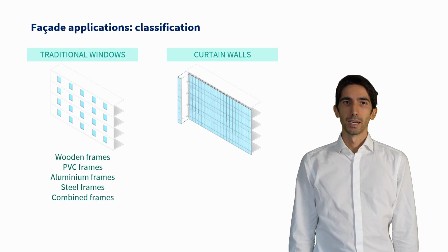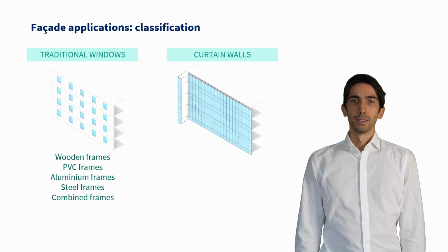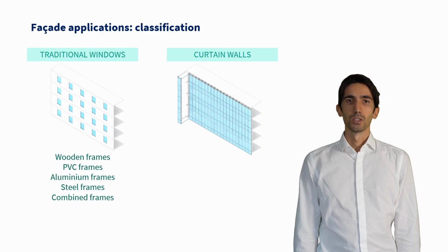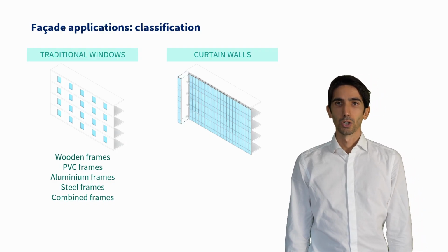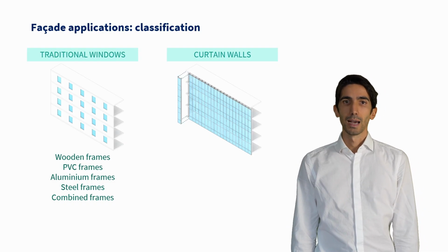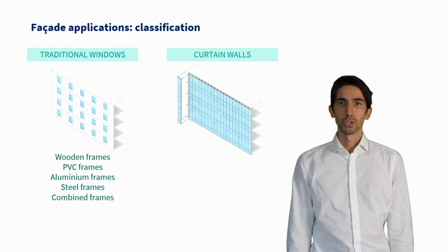These materials range from traditional wooden profile to PVC, aluminium, steel, or a combination of the previous ones, as better described later. The interface between glass and frames is usually solved thanks to the adoption of EPDM gaskets that allow to accommodate the tolerances and to assure the air and water tightness.